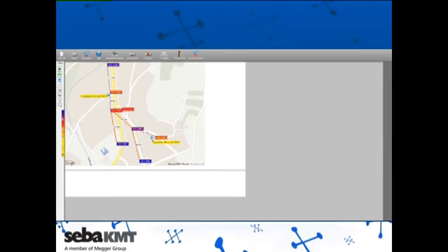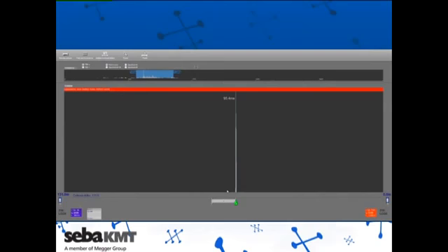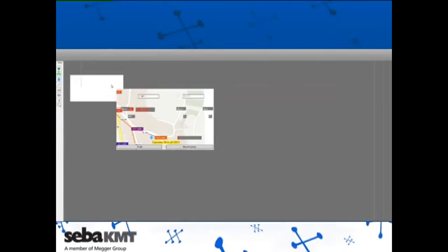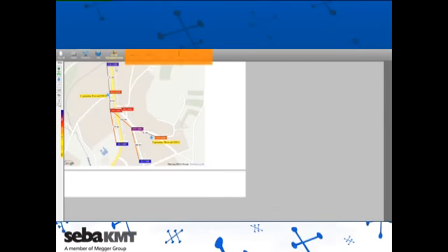Using the V-assistant function, we determined the sound velocity in the relevant pipe sections, which led to an increase in measurement accuracy. If we correlate between the sensors number 5 and 6, sensor number 5 is displayed as the leak point, which signifies a leak outside of the measured section. If we then correlate between sensors 5 and 1, we get a clear correlation result with the leak distance of 5 meters from sensor number 5.